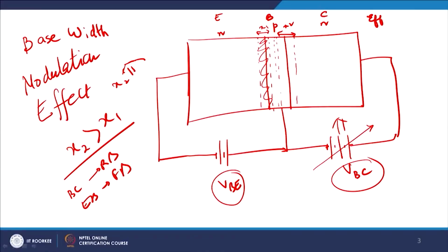you could easily appreciate that the effective base width reduces, fine. As it reduces, you allow a larger amount of current to flow through it, because now the number of minority carriers there, or the number of holes there, is still smaller. Is this concept clear? Therefore, I will explain once again what I was trying to say, because this concept will be important to understand why the collector current is not behaving as an ideal current source.